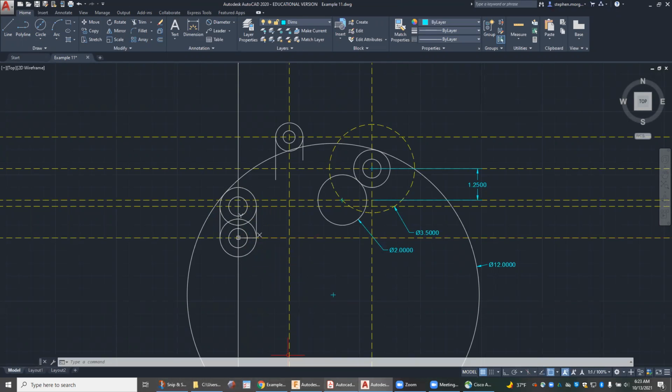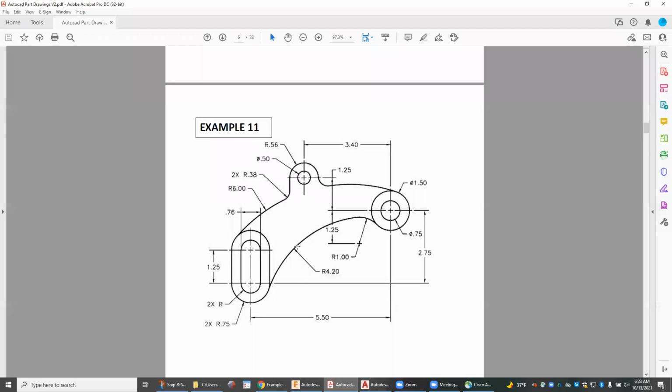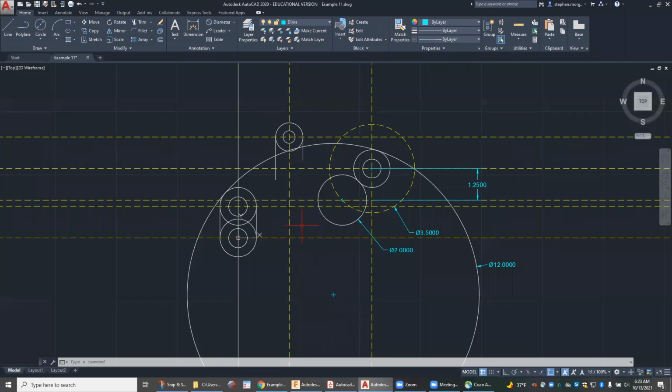Going back to the drawing, you're going to notice that we can actually use one arc on that top edge up here. If we look at the drawing, we end up doing a tan setup between these two. So tangent, and then a radius, which is 6, and you end up with a big circle going around that top edge.